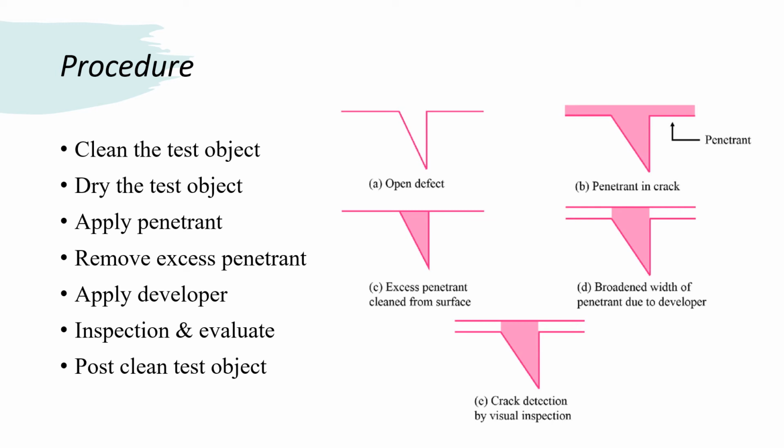Excess cleaning may remove the penetrant from the upper region of the defect, with the result that the developer does not reach the penetrant and no defect is indicated.